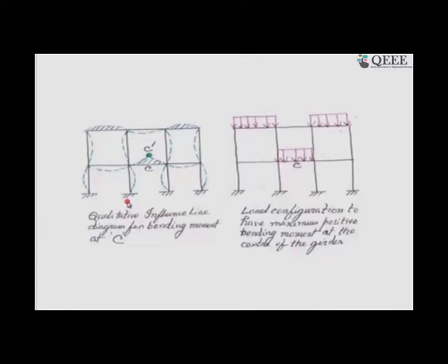We are interested in where that C is written, the bending moment at the middle of this, the influence line diagram for bending moment at the midsection. So, obviously, the midsection of a beam might be subjected to the highest sagging positive bending moment. That is why we suspect that it should be examined. Yes, and now we are examining with the Muller-Breslau principle. Now, how to apply the Muller-Breslau principle to this frame is exactly the same as we applied to the beams and the trusses and also the indeterminate structures.